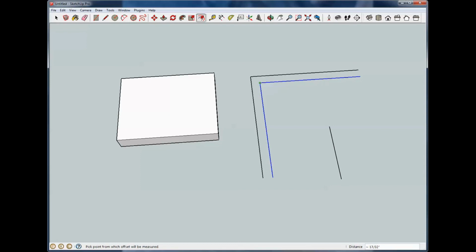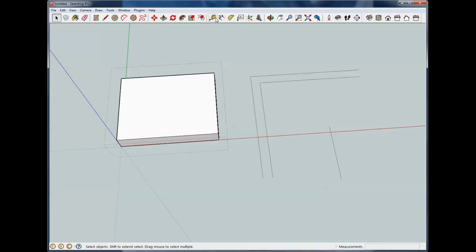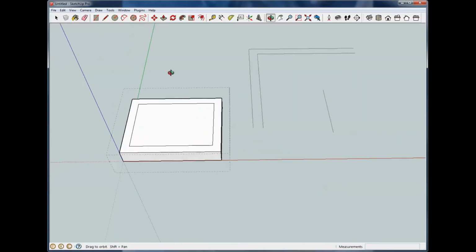See how that worked? Same thing here. We can go to offset tool. Oops, I got to get it selected. Offset tool, and start drawing our offset. So if we wanted, say, a 1 inch offset, we can just type in 1. We now have a 1 inch offset.